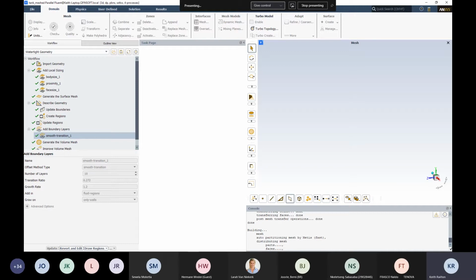Okay, so let's allow that to open for a little bit. Are there any questions with regards to the boundary layer and Y+? Hopefully, I have covered that. If you have any questions, feel free to ask. And I have a spreadsheet that I'll share with you. I'll put it in that file that we've been using. It's fairly straightforward. You specify a velocity, density, and viscosity, and a Y+, and then you can calculate the value from there.